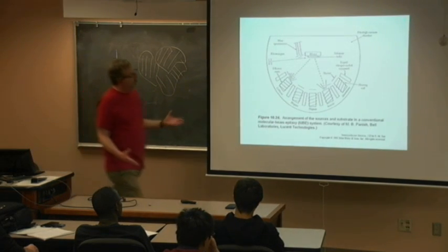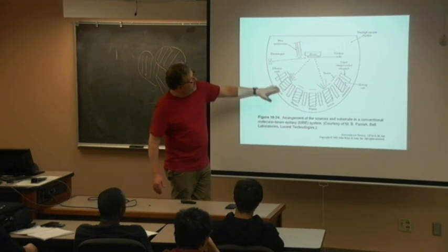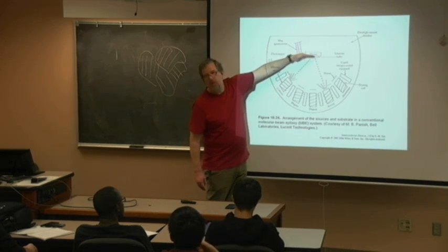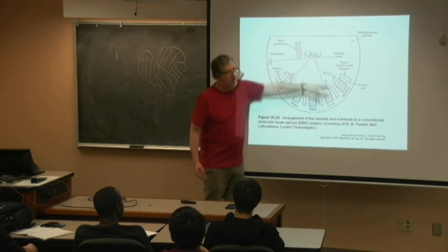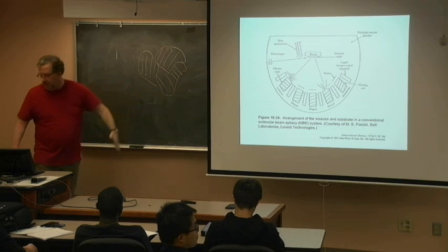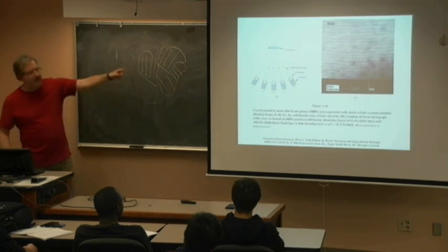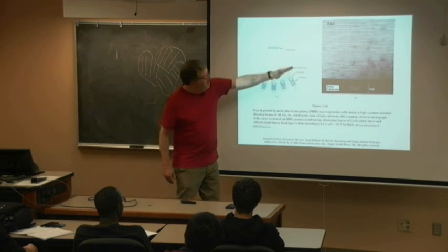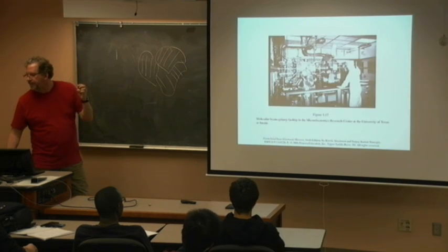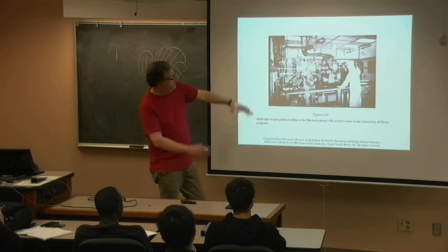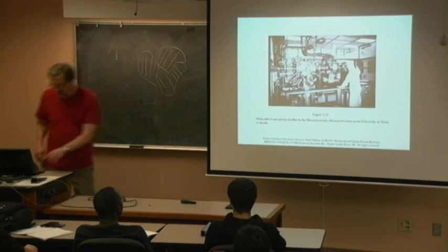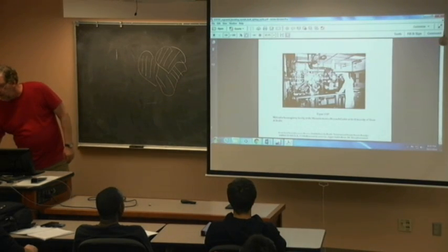Here's a molecular beam epitaxy. If I really want to get high precision, this is how most of my research samples are produced. We have effusion cells and they deposit, and we can deposit with atomic layer precision. And you saw already the reflection, the electron diffraction off the surface, so I can actually monitor that atomic precision. And here you can see a quantum well structure with atomic precision. That's a piece of cake these days. One of these is just a big chunk of stainless steel.